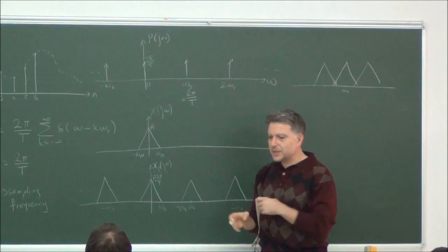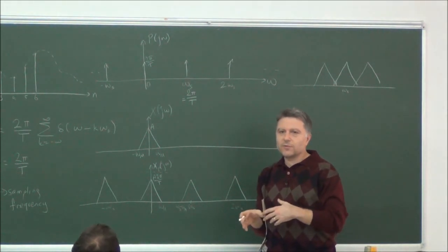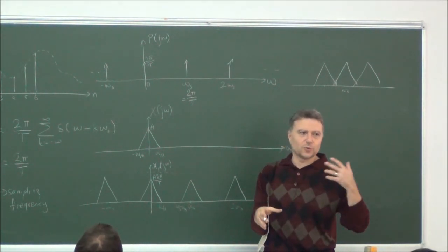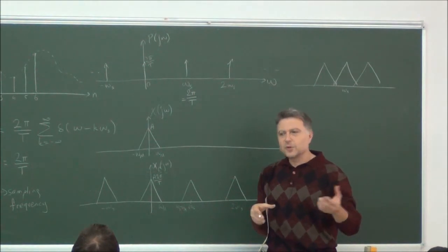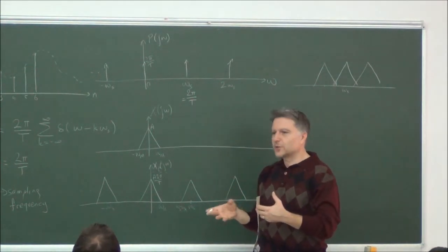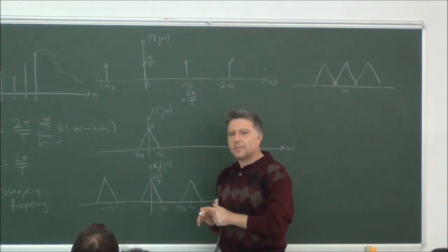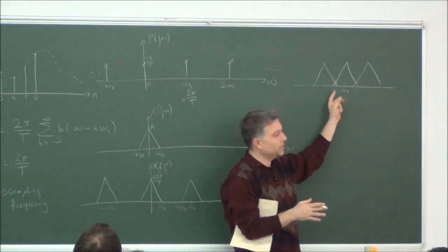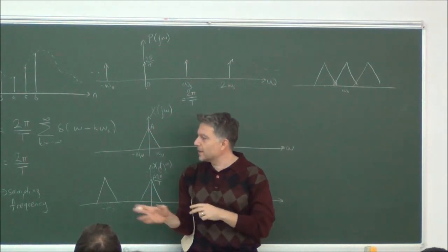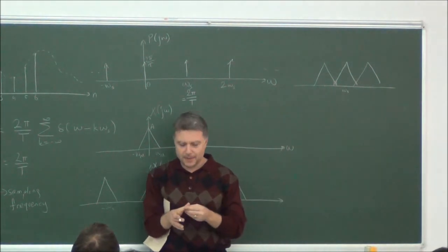And from that mixture, you cannot resolve which components correspond to the signal, which correspond to the other component. They are occluding each other. So it's a masking process, therefore. If you don't obey the Nyquist criterion, you have masking.